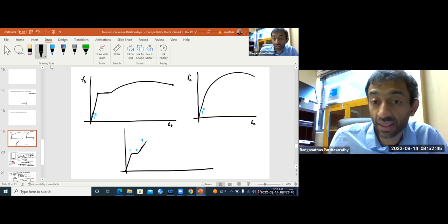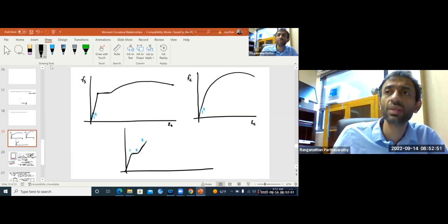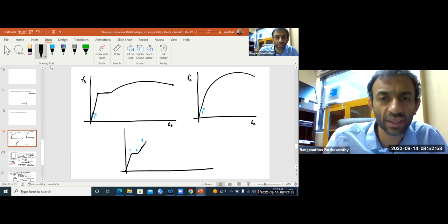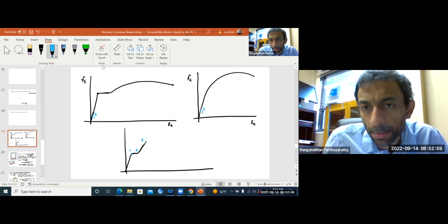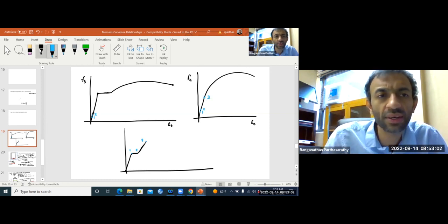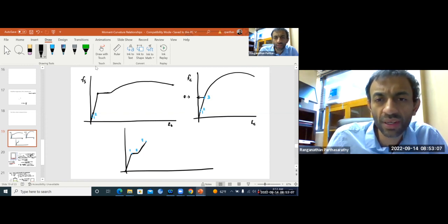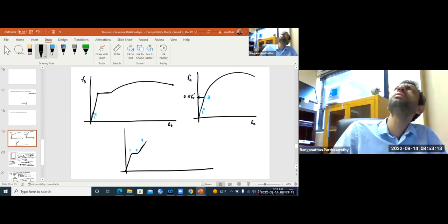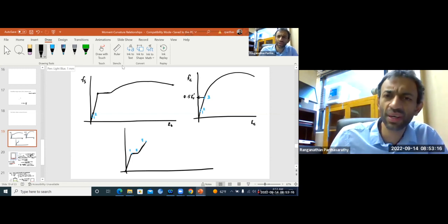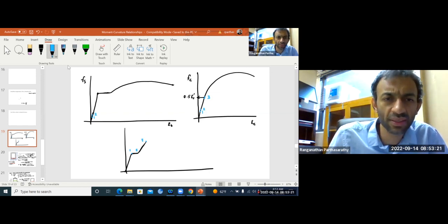Okay, so now we are at 3 here. So 3 was the proportional limit of concrete. So 3 will be here. This is 3, and here you can take concrete stresses 0.5 Fc prime, or 0.7, 0.5 is okay. Okay, this is 3, 0.5 Fc prime, and the steel will still be somewhere maybe there.